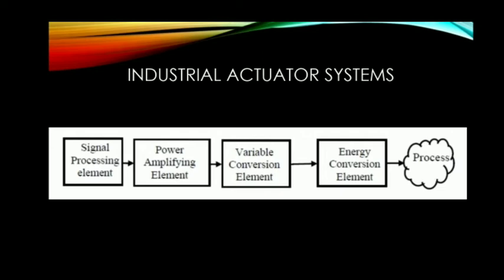In most cases, actuators are devices that first produce motion from electrical signal, which is then further converted to other forms. The electronic signal processing element accepts the command from the control system in electrical form. The command is processed in various ways. For example, it may be filtered to avoid applying input signals of certain frequencies that may cause resonance. Many actuators are themselves closed feedback controlled units for precision of the actuation operation. Therefore, the electronic signal processing unit often contains the control system for the actuator itself.